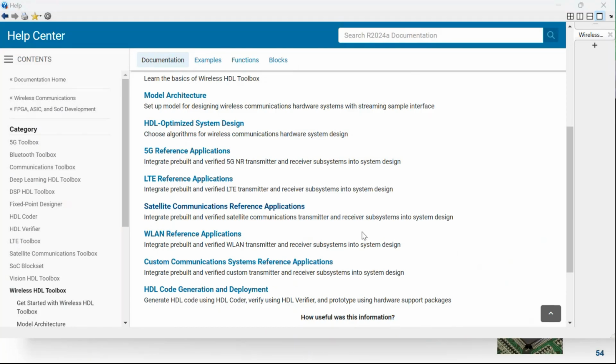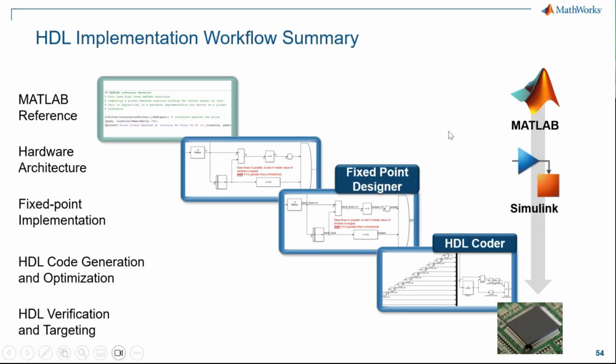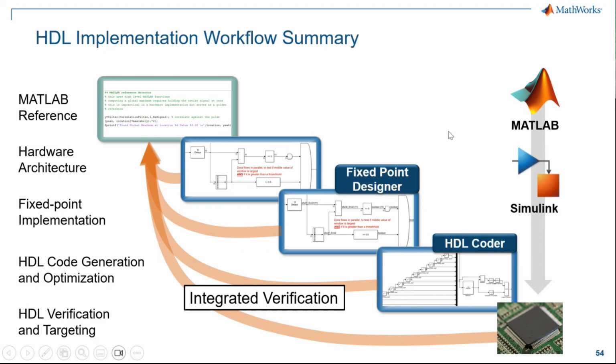What else? I probably have a few more slides, but I'm not going to go into the details. Just to conclude with this implementation, what is interesting is that we've got tools to facilitate the conversion from floating point to fixed point. Here, depending on the target, in MATLAB or Simulink, you can tell, okay, these are the limits of the signal I want to use.